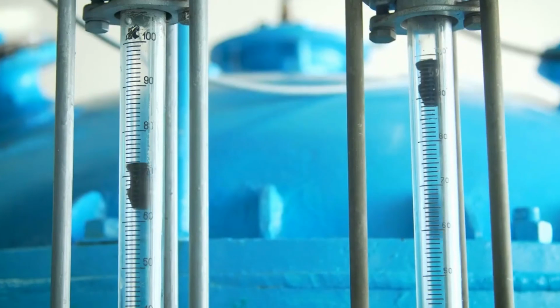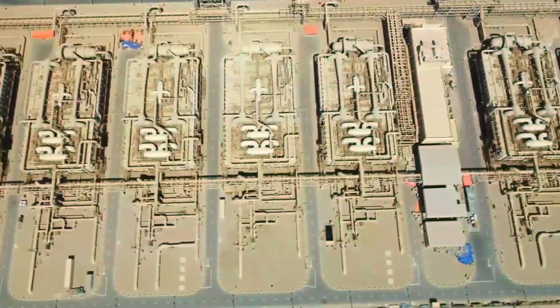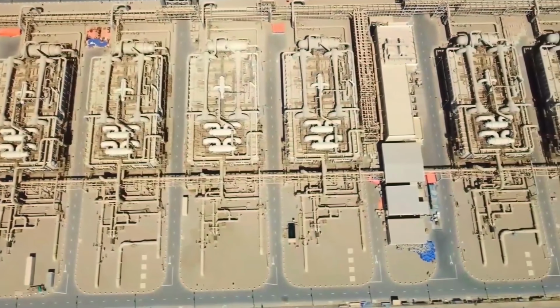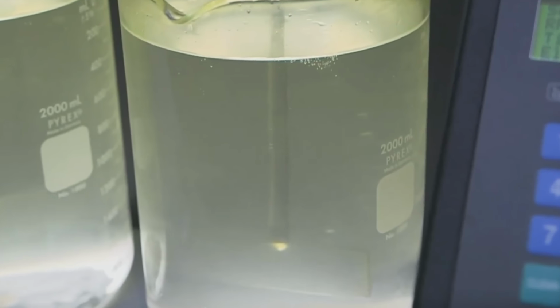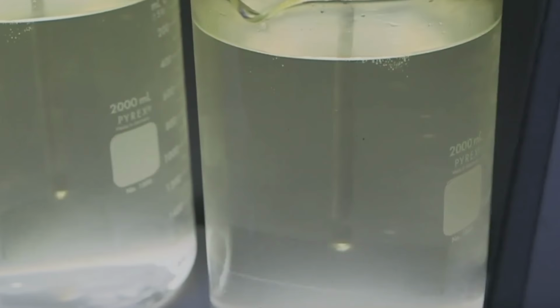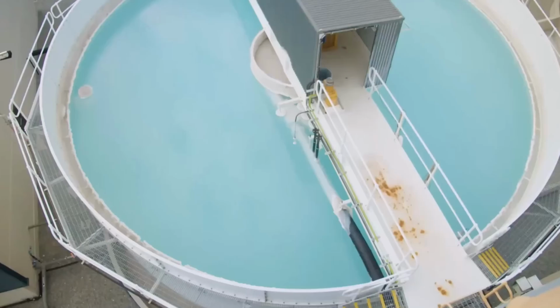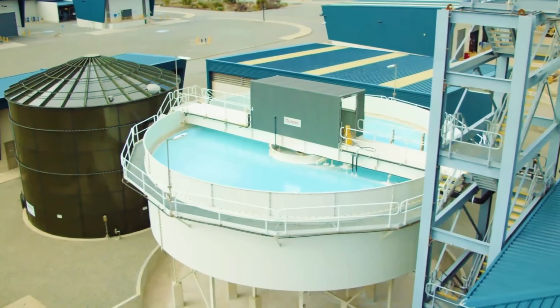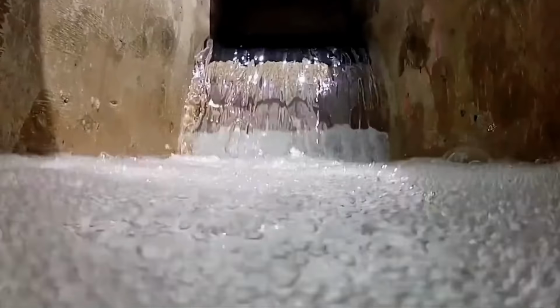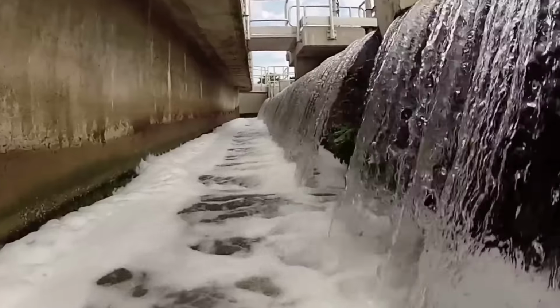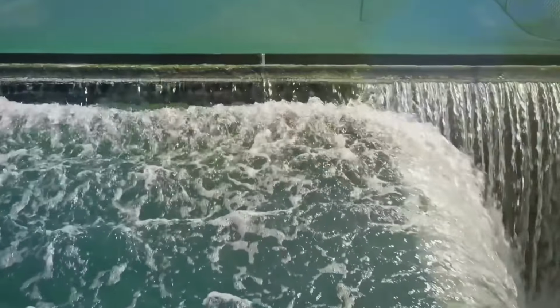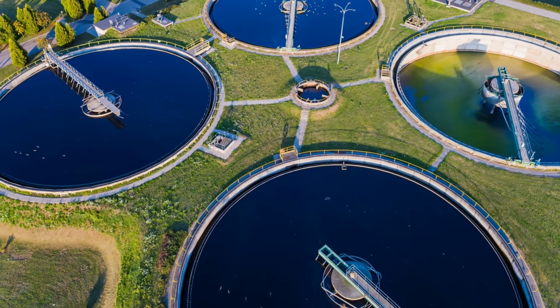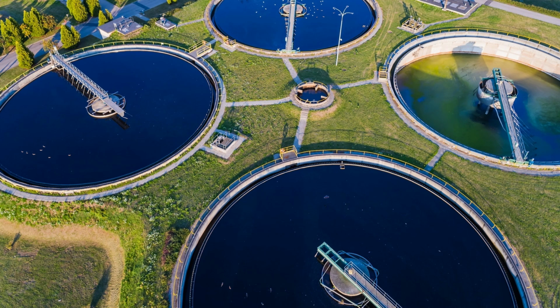The finished water is continuously monitored before it leaves the plant. Instruments can detect changes in salinity and conductivity almost immediately, while additional tests check chemical and microbiological quality. Once it meets the required standard, the water can be pumped into storage reservoirs or directly into a larger municipal network. In some systems, desalinated water is blended with water from reservoirs, groundwater, or conventional treatment plants before reaching consumers.